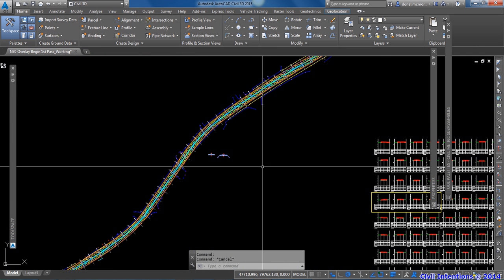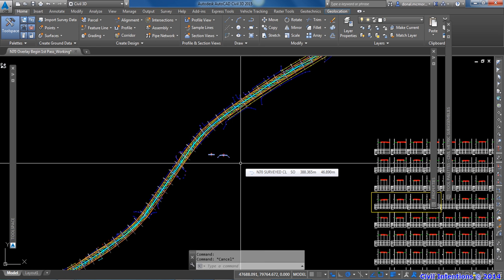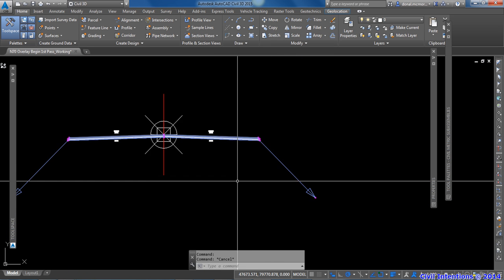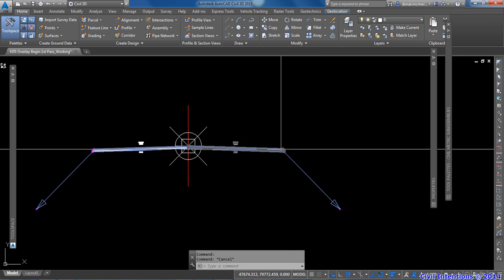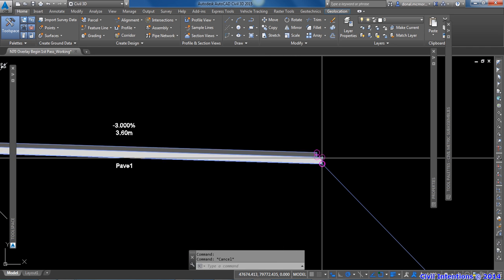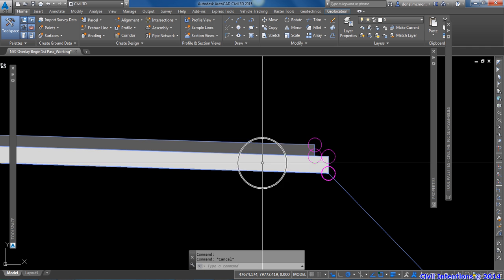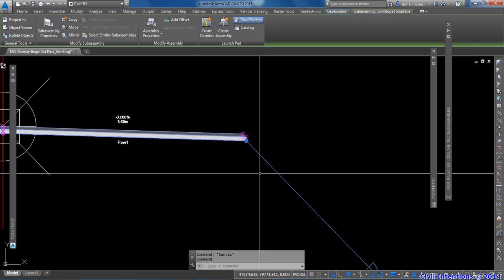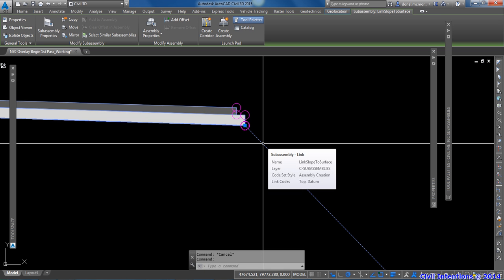And because we're just hanging our assembly or corridor effectively off that smoother profile, we're just going to use the normal standard lane sub-assemblies or one of those. Okay, so the assembly we're going to create, this is the finished article here. I'm going to recreate this in a couple of minutes, but just to show you what it is first, very simple. It's an assembly with two layers to it. So we've got a 40mm wearing course over a 60mm binder course, and then you have a link here. I suppose for the side slopes of the regulation material, it's just sloping back down to the existing road surface at 1 and 1.